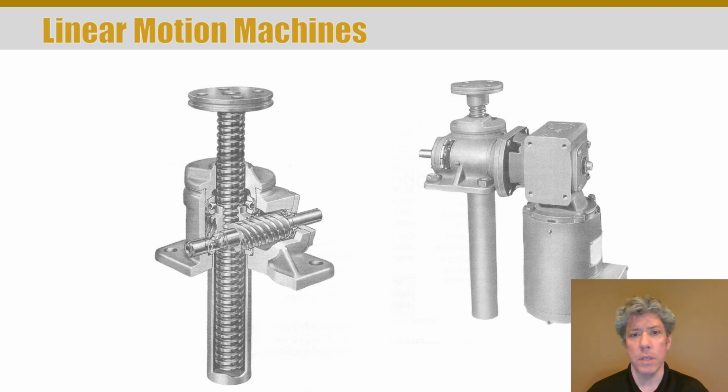And so there's a tremendous reduction in speed. Of course, that looks like it's about a 4-start worm. But there's a tremendous reduction in speed still from the worm to the worm gear, and so there's a corresponding increase in torque and therefore force in order to drive this screw thread, which is what is properly called, up or down in that fixture.